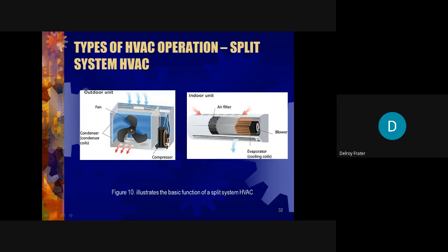And then when the temperature begins to drop by virtue of the number of persons in the room, or persons frequently opening the door to let hot air come in, that starting current is always 6 times or more than the running current. So that causes you to burn a lot of energy.